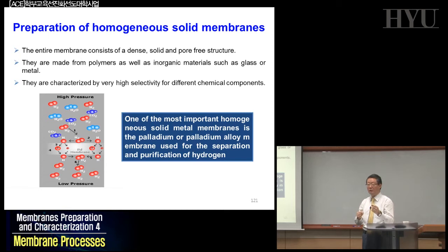And that way you can easily fabricate your zeolite-polymer blend membrane. And the second step will be removing this polymer at high temperature, such as I think 600 or 700 degrees C, so that you can burn this polymer out and come up with a relatively flexible, I would say, remaining framework of the zeolites. It's not like a polymer, but it's relatively flexible.